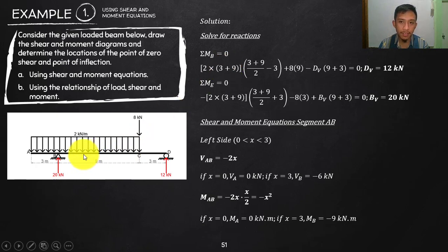So 12 divided by 2 is 6, minus 3. So that is the moment arm, and that will be clockwise. Again, the concentrated equivalent of this is somewhere here in the middle, located at a distance 3 from your point B, where we are getting the summation of moment, and that will make it clockwise.